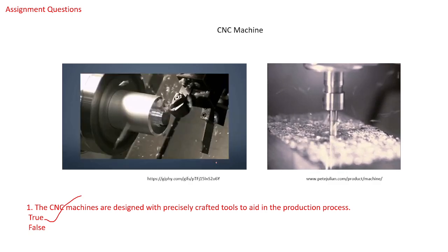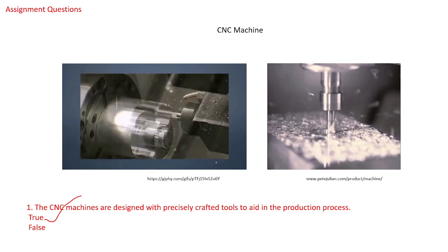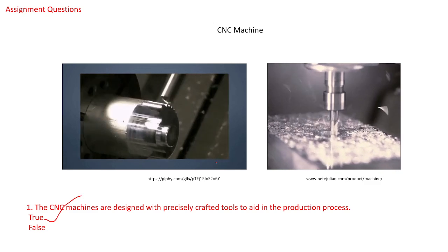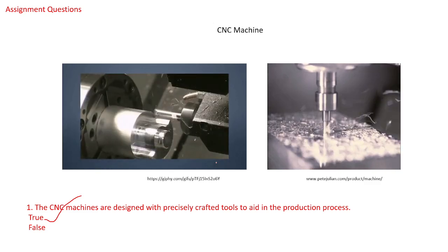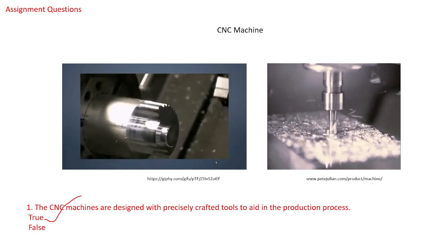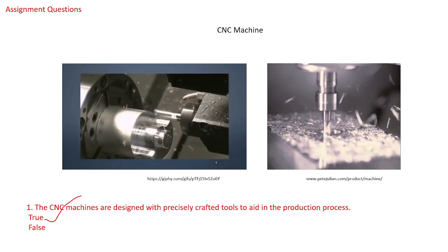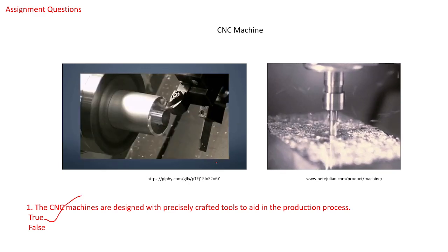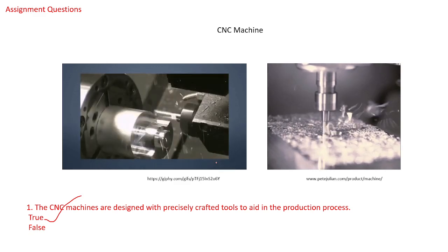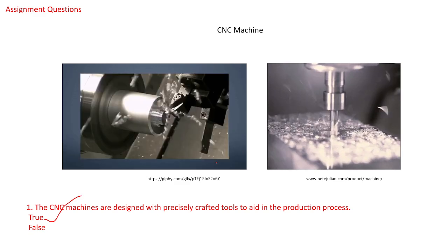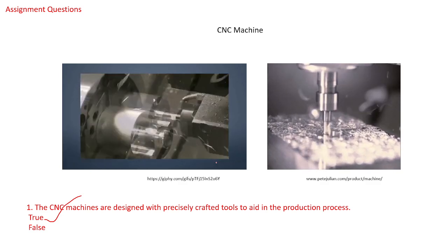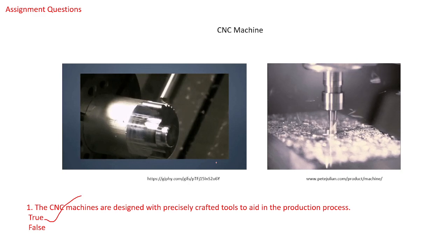So what does CNC turning mean? CNC turning is a precise and efficient machining process that works on the principle of the lathe machine. It involves placing the cutting tool against the turning workpiece to remove material, and it finally gives us the desired shape which we require, right? The turning center or lathe stays secured while the raw material rotates at high speed.